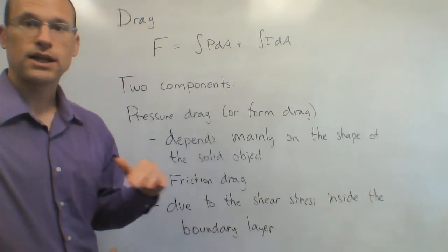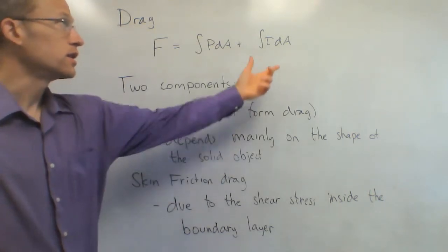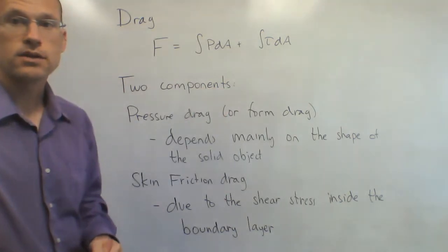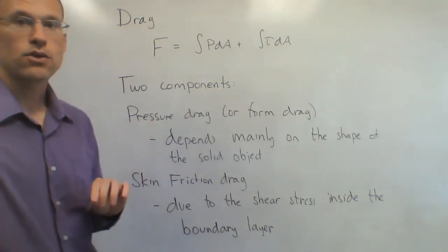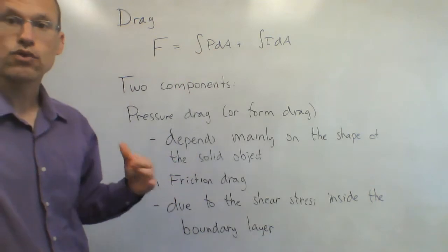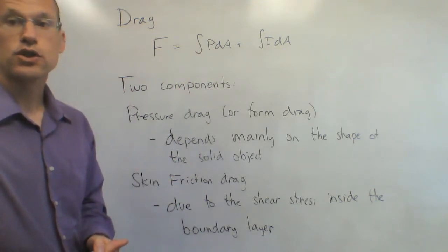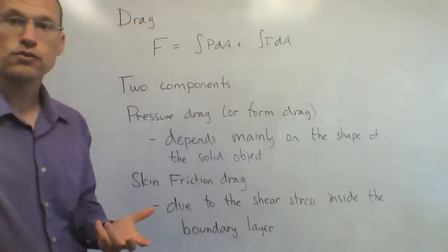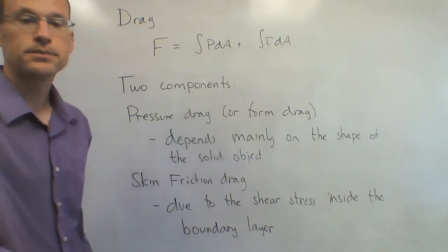For the flow over a flat plate, that drag force was just the skin friction drag because it was a really thin flat plate, so there's nowhere for any sort of pressure variation. So we were assuming that the pressure contribution, the form drag, was zero in those cases.